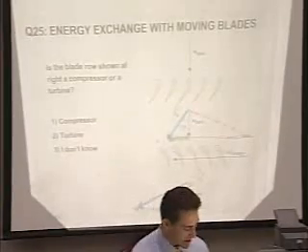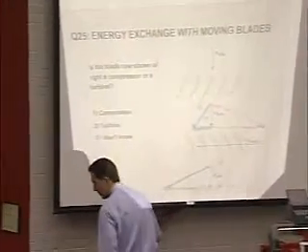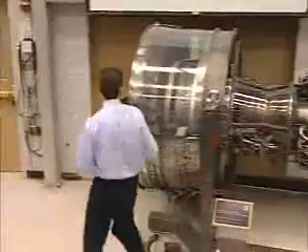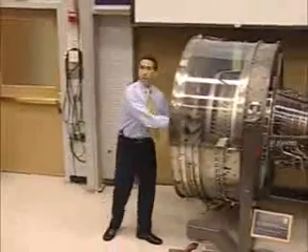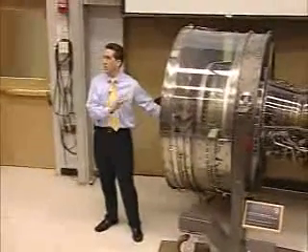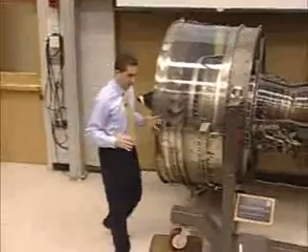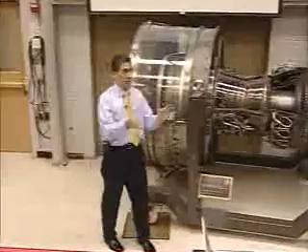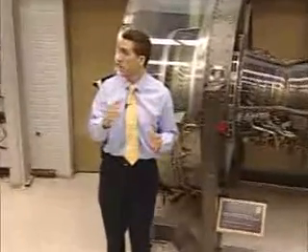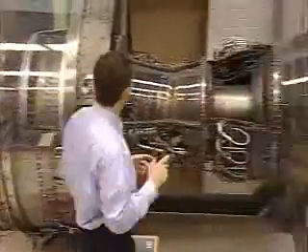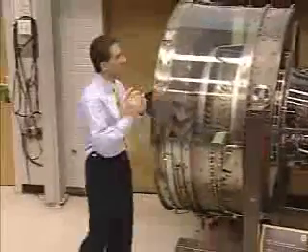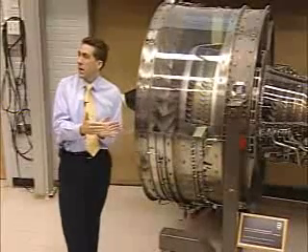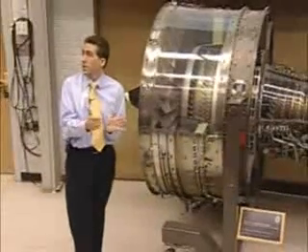So again, I would just think about yourself as a fluid particle traveling through this engine. You come in and you've got no angular momentum, and then whammo, you hit these blade rows. And now your flux of angular momentum is changed. You have some positive flux of swirl going through the engine, and each one of these blade rows keeps changing that as you go through. And it's only the moving ones that add the energy. The stationary ones just convert it from swirl back into the axial direction, and in doing that, convert it to internal energy.